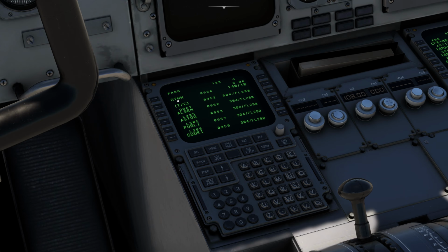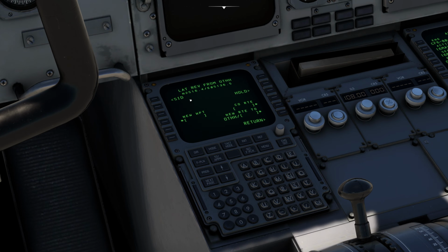The departure airport is shown, and plus this is a point at which you will be reaching the top of climb, the cruising altitude. Then you have the airways L305, and it will take you to Astog, and then L305 to Burli. All the waypoints and the airways are shown. Now over here in this flight plan, you have to select the departure procedure. Just click OTHH, and it will ask you to enter the SID. Simply press this option, and then you can select the runway.